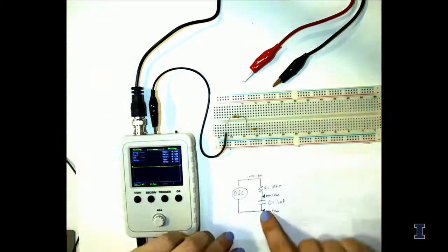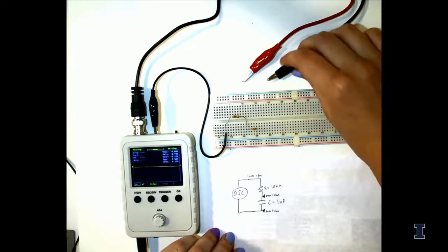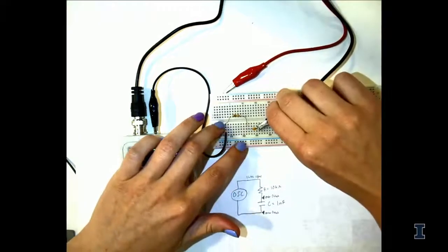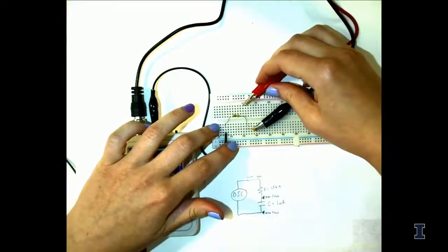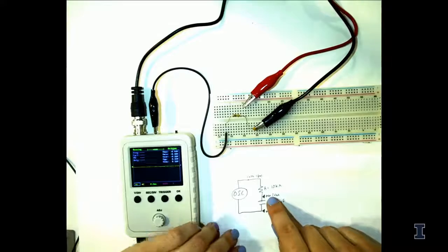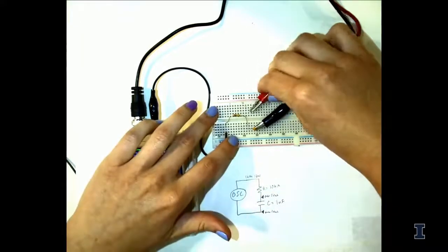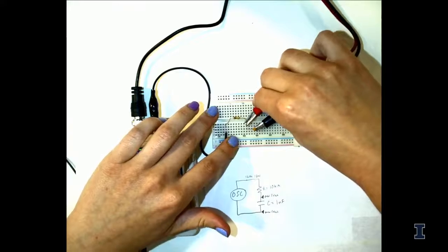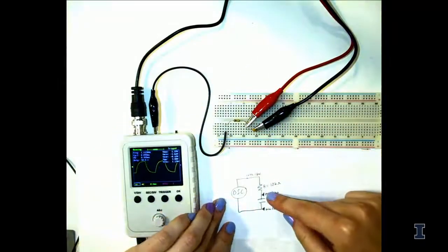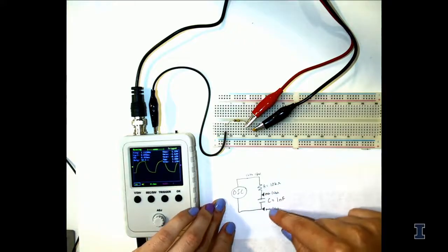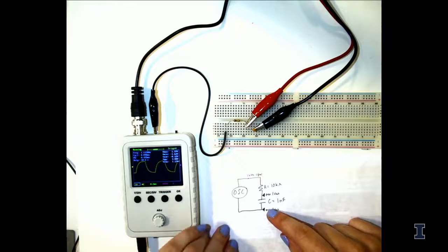Finally, to complete the circuit, we need to put the black probe against the capacitor. And then the red alligator clip is going to probe in between the resistor and the capacitor. So you can do that just by adding it to the leg there. And this allows us to measure the voltage across the capacitor, which we'll notice there's a change in it.